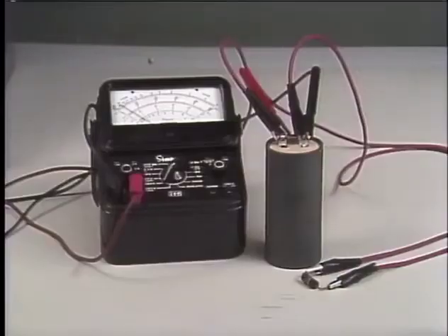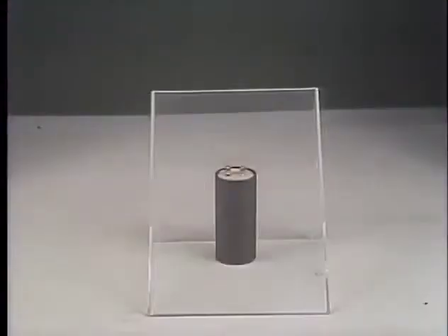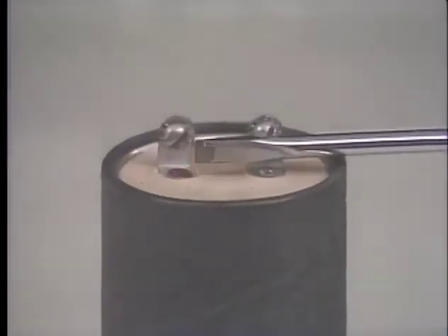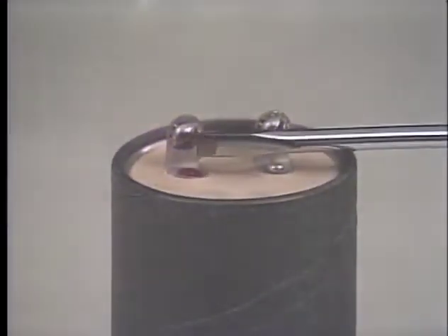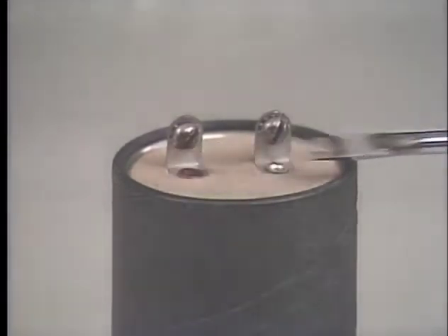The waiting period is necessary because the capacitors will hold a charge for a period of time even after they've been separated from their source of energy. This stored charge can be very dangerous. The potential hazard can be demonstrated with a small capacitor that is commonly used in electronic components. This capacitor was energized, and then the source of energy was removed. If the terminals of the capacitor are shorted together, the charge in the capacitor is released rather violently, and this is a small capacitor compared to the capacitors used in substations.